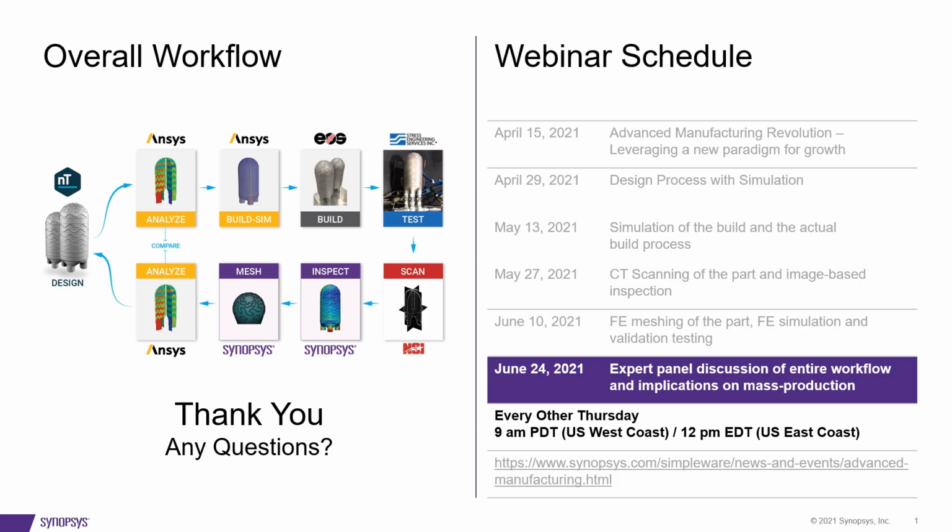Great. And a question for you, Matt. Have you planned also to perform cyclical testing and high temperature tensile testing? We don't currently have that planned in this scope of work, although I'd love to be able to do that on this part. We could have a test rig where we can apply cyclical pressures from, say, 0 up to the operating pressure, thousands or 100,000s of times. It'd be really interesting to see how fatigue affects some of those internal cavities with the surface finish from the 3D print. And then we can also do that at elevated temperature.